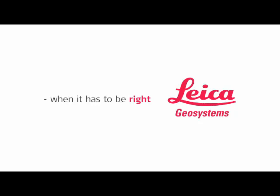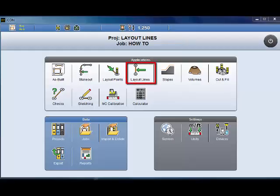Layout Lines how-to video. The Layout Lines application is used to place marks in the field at predominant points where the points are to be set up. These points can be part of a line or an arc. The application offers the possibility to lay out control lines, parallel and perpendicular lines, and it also aligns structures in